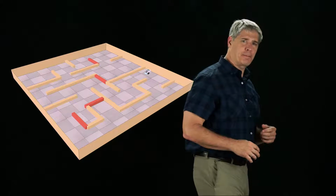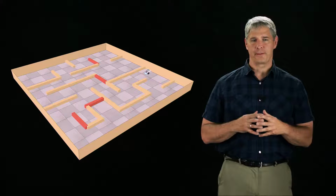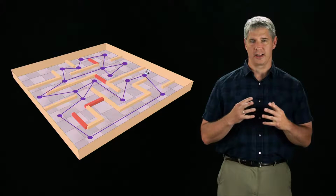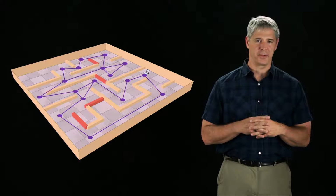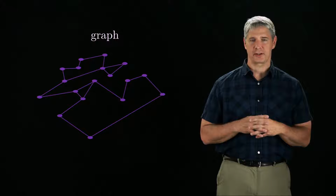Although the C-space of a robot is a continuous space, in motion planning we typically discretize it in some way. For example, this image shows a mobile robot in a maze. We could represent the free space of this maze by sampling some free configurations and drawing lines between configurations that can reach each other by a straight line path. This graph is now our discretized representation of the free space.